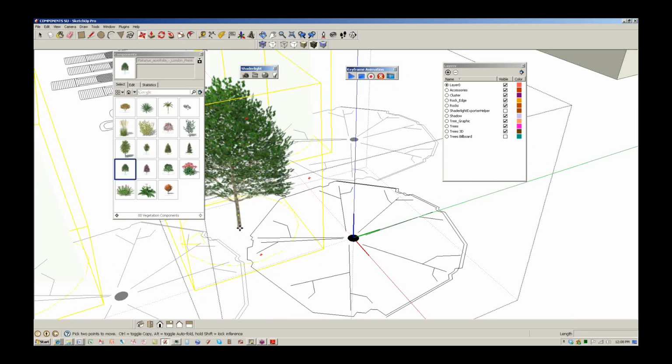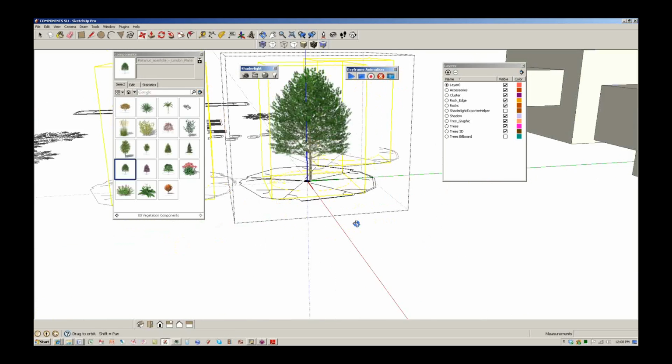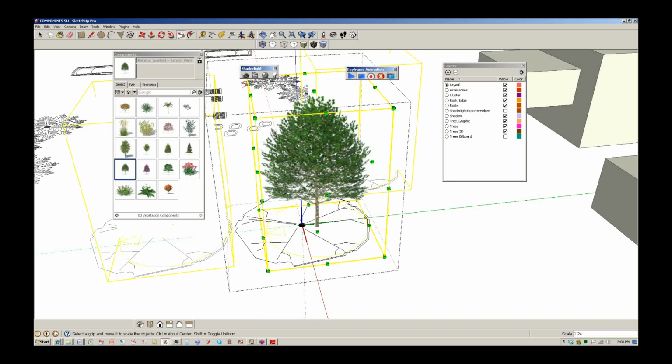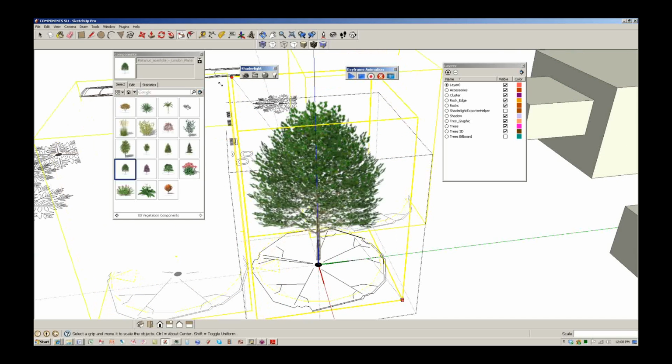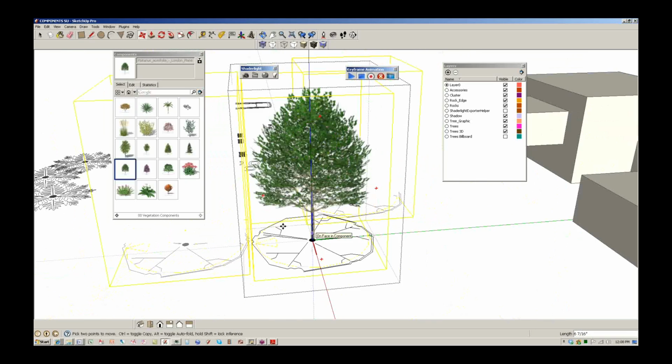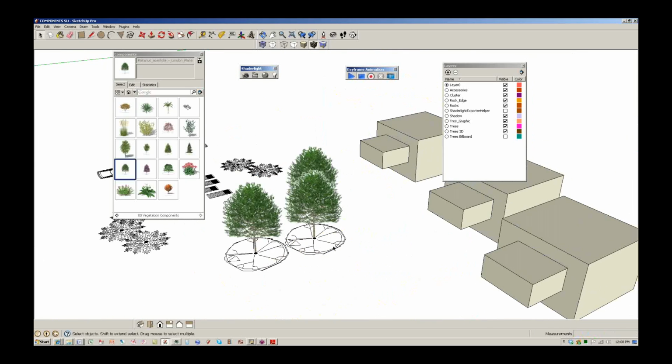Let's say you did it with the reload and it came in and it wasn't the right size. Well, based off my symbol, I know what the size of the plant should be. This way, I can scale it upwards or downwards to match what I know the symbol size is. So by doing it this way, yes, it is easier to reload it. But by doing this edit method, you're providing a lot more control over what you're bringing in, and you don't have to figure that out later where you're like, wait, that doesn't look right. Does that make sense? Yeah, reload's almost like a generic thing. It is a generic thing versus going in there and actually replacing it in this capacity.